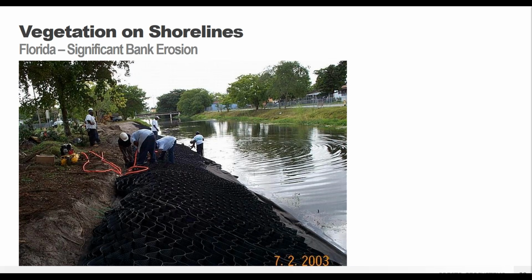You can install the GEOWEB system when it is fully wet, like you see here. The panels themselves will float initially, but then you stake them down. They'll hold themselves to the channel face, fill them in with your infill material, and the system is not going to go anywhere.